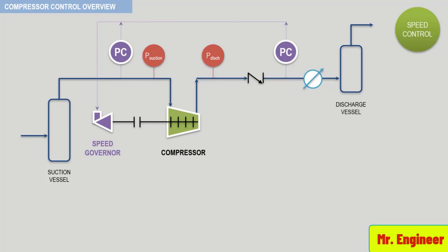However, the output of the controllers is run to the driver speed control system. In this manner, the exact amount of energy required to meet the process requirements will be applied, thus optimizing the efficiency of the process. In this system, the compressor produced energy is varied to meet changing process energy requirements.